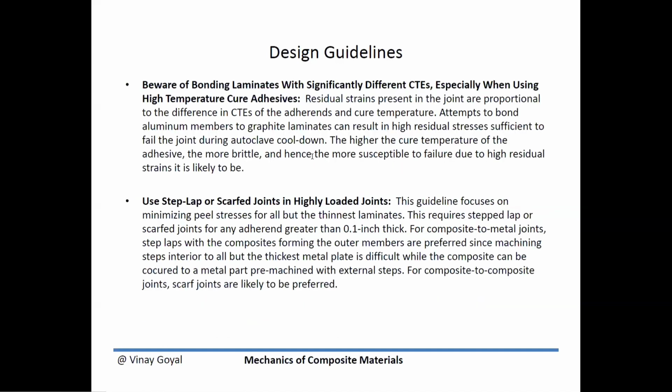Be aware of bonding laminates with significant amount of different CTEs, especially when using high temperature cure adhesives. So that's a similar derivative of the CTE things that we already talked about, but residual stresses present in the joint are proportional to the differences in CTE of the adherends and the cure temperature. So you want to decrease the residual stresses by reducing the mismatch in CTE. We kind of cover that in a different context, but it's the same idea.